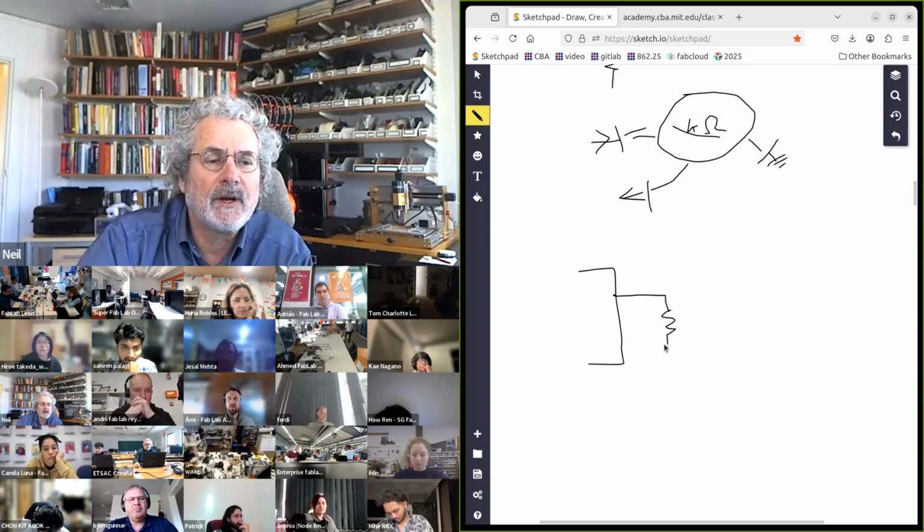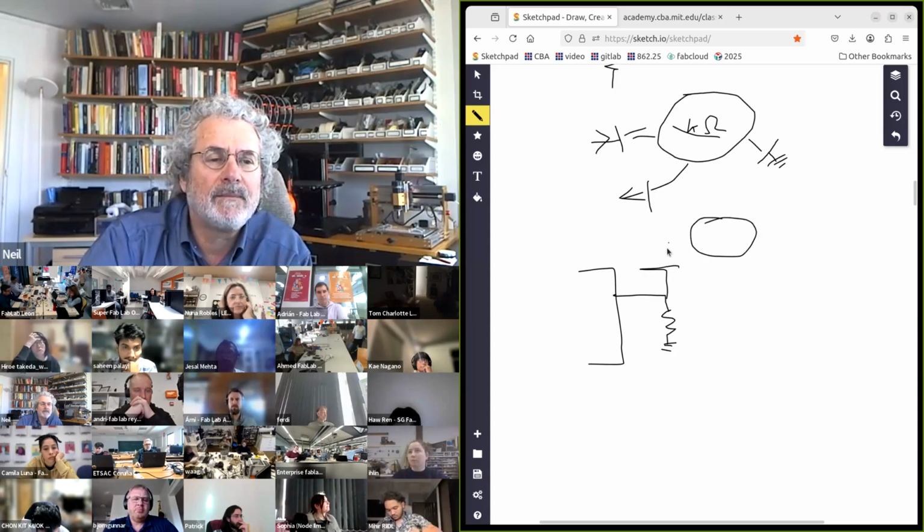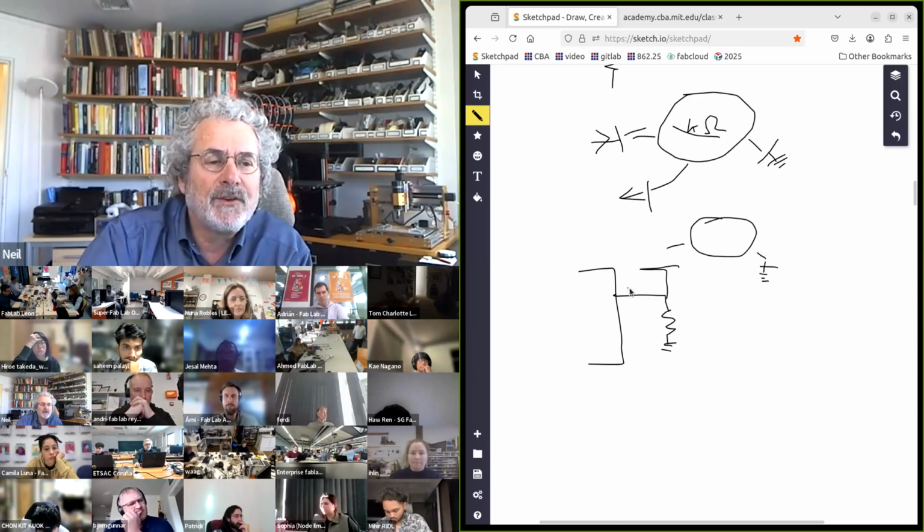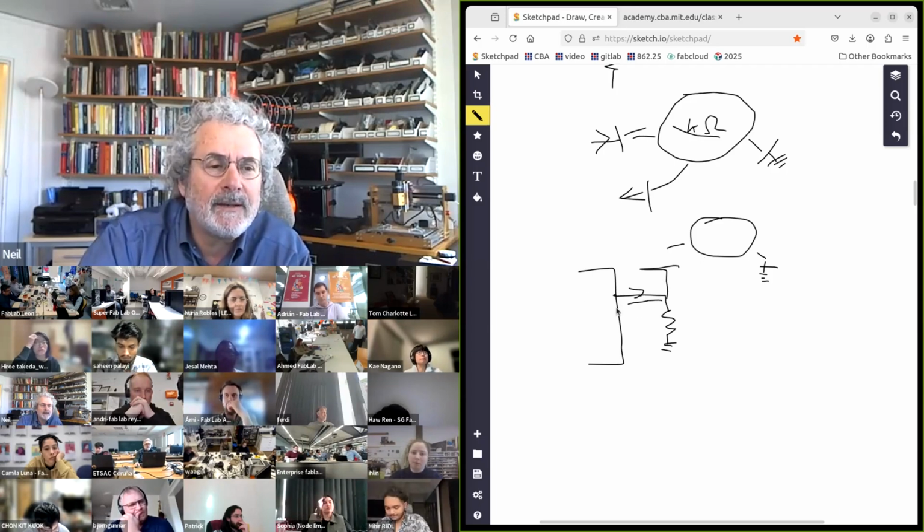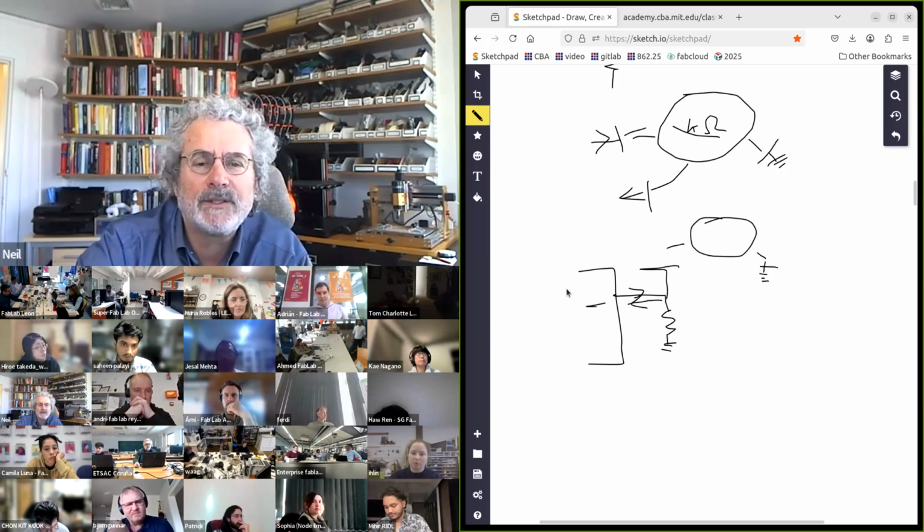So what I'm going to show you next is I have a resistor going to ground and an electrode. Here I am. It's going to couple through me to the outside ground. And I'm going to first charge up. Then I'm going to switch this from an output to an input, and I'm going to listen to it charging down.